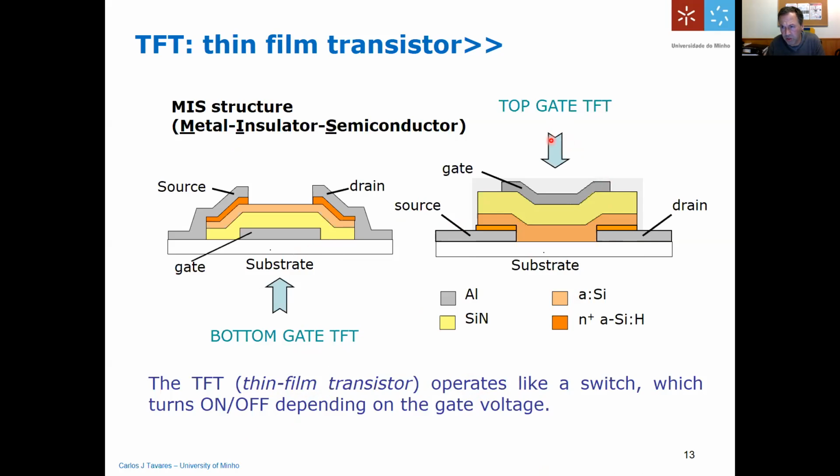We're going more into microelectronics, which is not my scope for this talk, but it's only an example to show you how you can produce different types of layers of materials to produce a device. You can do this by a combination of methods: CVD for the oxide materials or the nitrides, and sputtering or thermal evaporation for the electrical contacts. We'll start off with a substrate, for example, a silicon substrate.